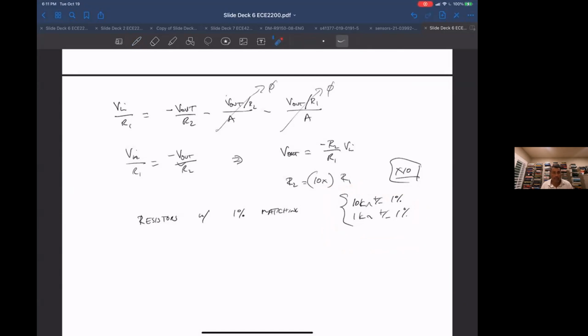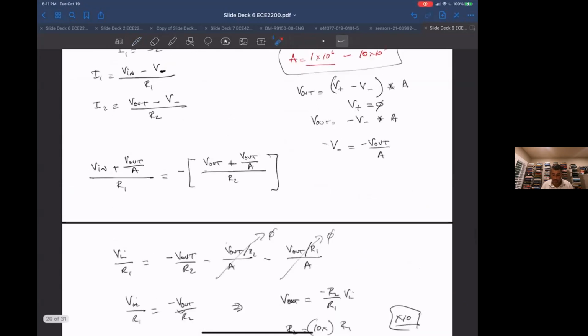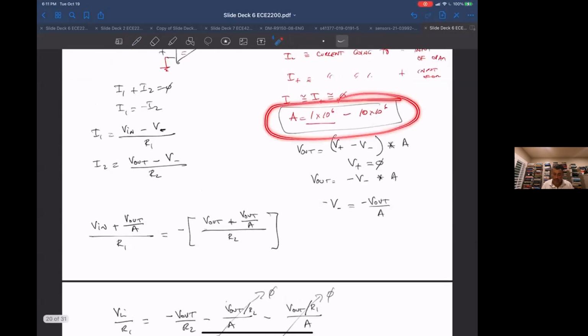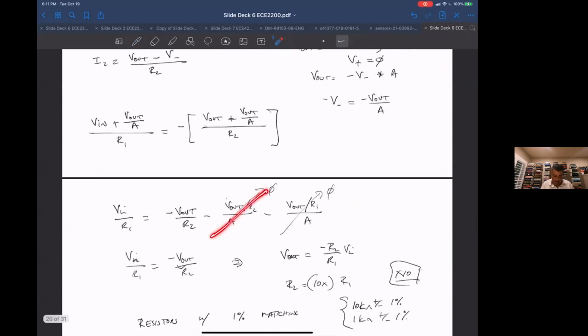Now, again, assume as temperature changes, the gain of your op amp goes from 1 million to 900,000 or 700,000, or goes from 1 million to 2 million. It doesn't matter. It's just this error, because either way, you're sending these guys to be approximately zero, or very, very close to zero compared to these values.